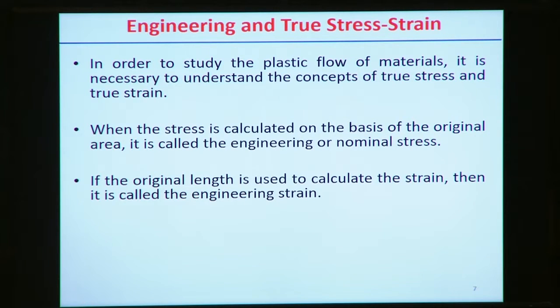Now it is very significant to analyze the engineering stress-strain curve and where it is applicable. In order to study the plastic flow of materials, it is necessary to understand the concept of true stress and true strain, because true stress and true strain rely on the instantaneous deformation or stress value during the application of the load.